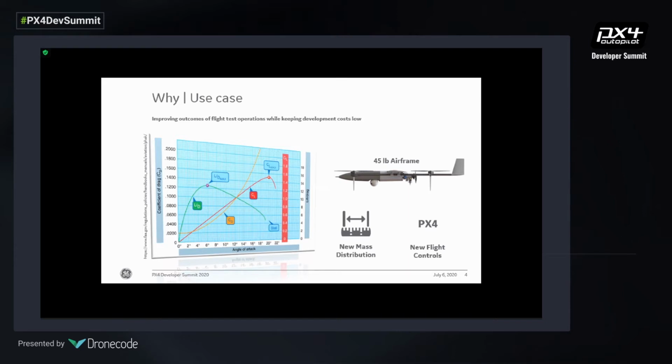And so we took the opportunity to model the airframe, effectively creating a digital twin that allows us to take that vehicle, evaluate it, train it, give our flight crew members the opportunity to actually see and feel the vehicle in the simulated environment, plus identify the way that we could either improve that static margin or overarching increase the performance of the vehicle prior to actually conducting that first flight.